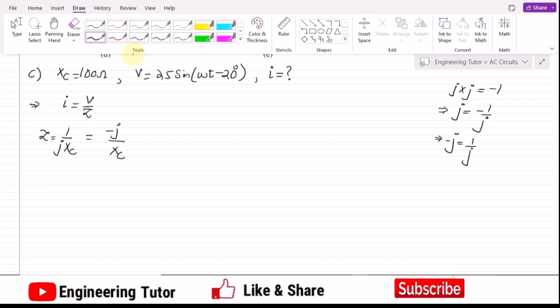Okay, so by using this rule I have used it here, minus j over X of C, so that is 100, and here it would be minus j 0.01. In rectangular form it would be 0 minus j 0.01. In polar form the amplitude will be 0.01 and the angle with it will be, because this is minus j, minus 90 degrees ohm. So that is the impedance here.